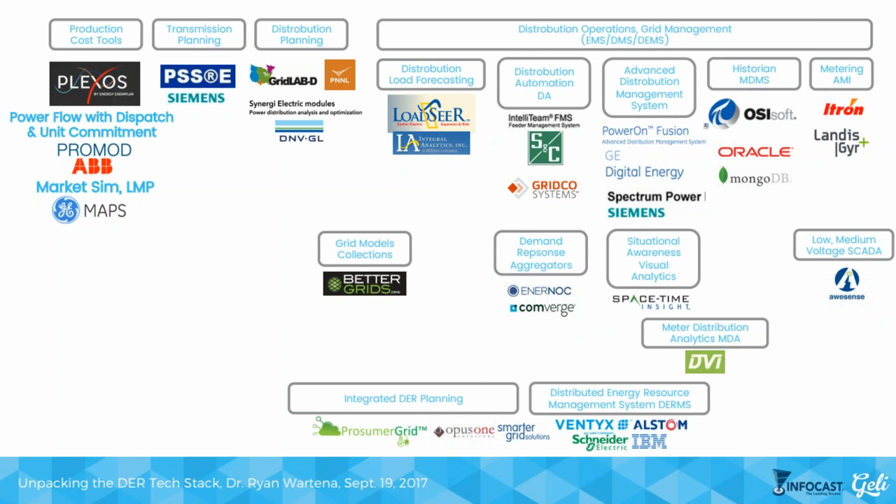And it wouldn't just be about automating demand and DERs, but also integrating the planning, because really it's about where you locate DERs. So you need to have the low voltage, medium voltage data coming into planning almost in real time, not in a 10-year long-term procurement process. You need that also, but also in a real-time loop where that low voltage, medium voltage AMI data is coming into an integrated DER planning system. And then that output is going into operations and the dispatch sequences and power flow constraints on the distribution system.